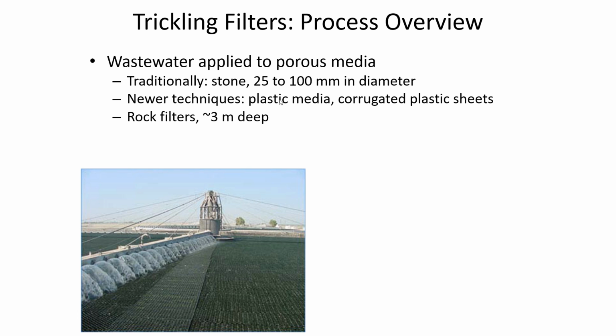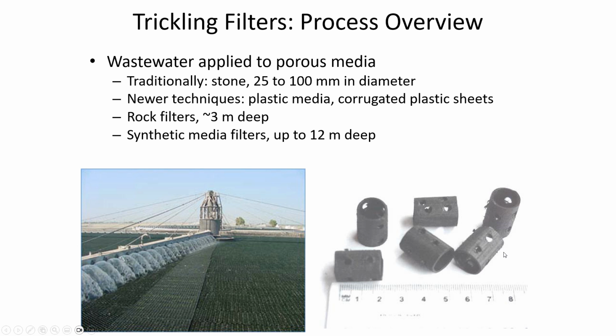to the bottom. In the case of rock filters, they may be as much as 3 meters or 10 feet tall. You're able to go quite a bit taller if you use plastic media because it's less dense. So up to 12 meters deep potentially if you're using a synthetic media. And this is just a look at what it would look like.